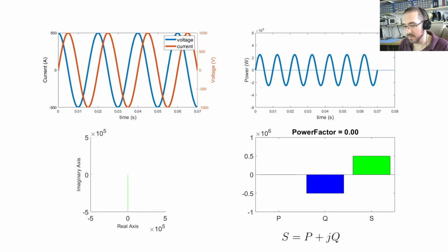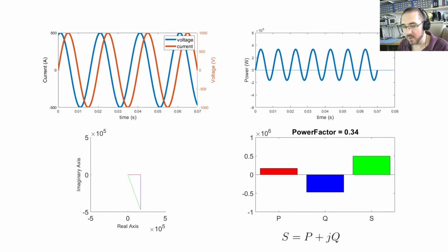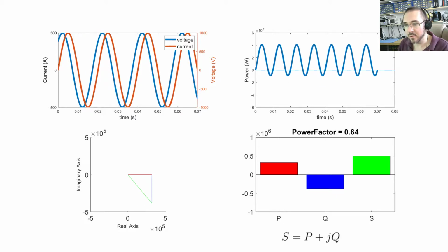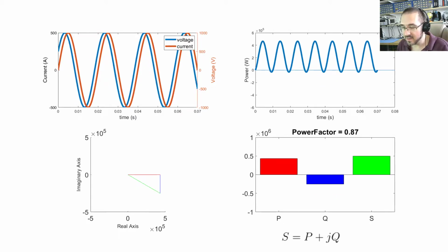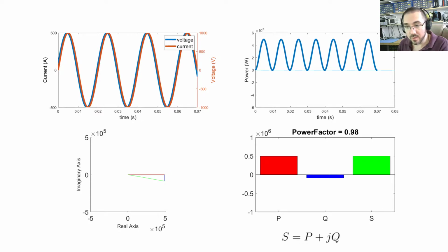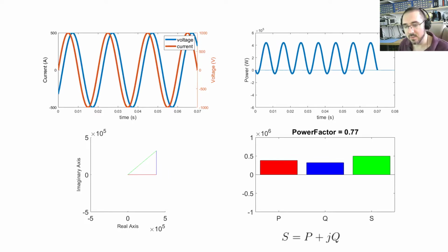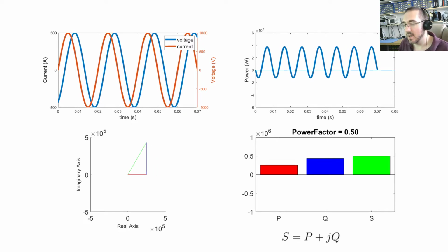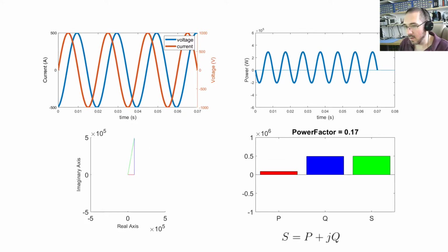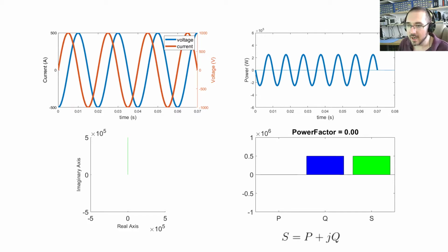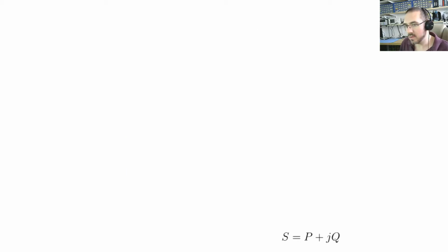And as I said before, complex power is a way for us to split the power up into two separate things. The phenomenon that causes these things is separate. One of them is caused by inductors and capacitors. The other one is caused by resistors. They combine as complex power, but fundamentally it all goes back to the phase shift between voltage and current and the all-important dip below zero.